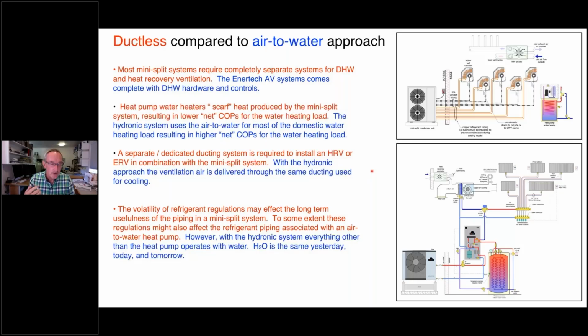When you do a hydronic-based system, you don't have to worry about the chemistry of the fluid changing. Water is going to stay the same. So one of the virtues of a hydronic system is that when it's properly designed and maintained, that water-based system really doesn't care what's adding heat or adding cooling to the water. It's still going to be able to flow through the pipes, and it's not subject to the regulations compared to what we have with refrigerants.